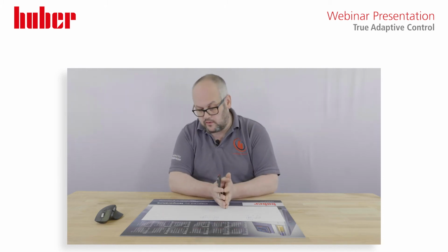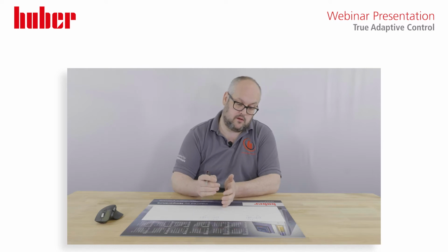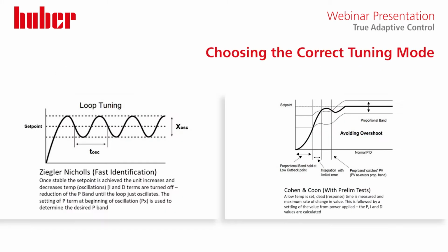How do we tune the PIDs of these two different styles of units? In the Huber unit, if you go to menu, temperature control, TAC, auto configuration, you will see that you have the option to do PID tuning fast or preliminary with testing. If you read into your PID terms, Ziegler-Nichols is the fast identification method.